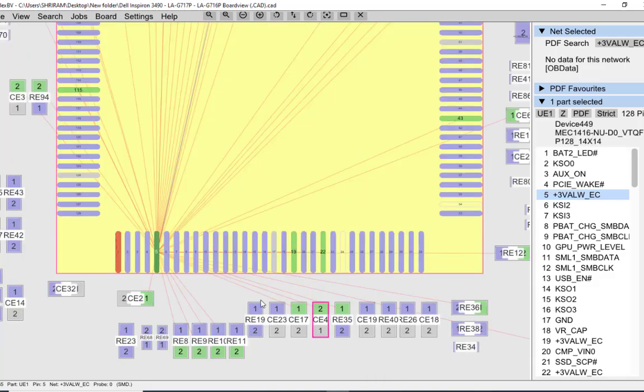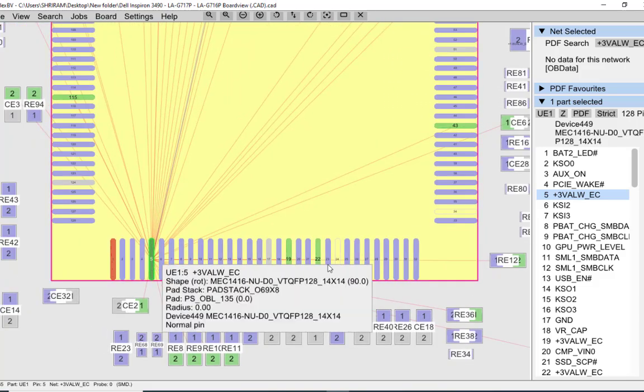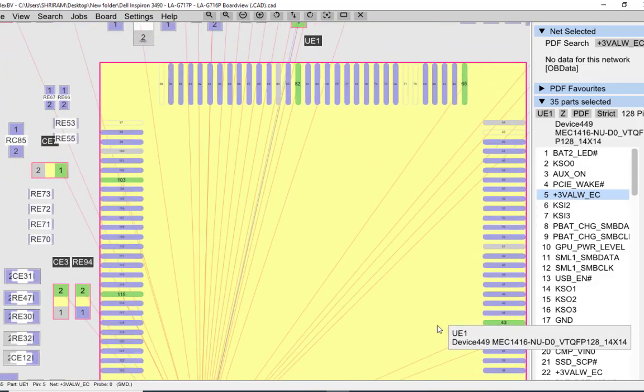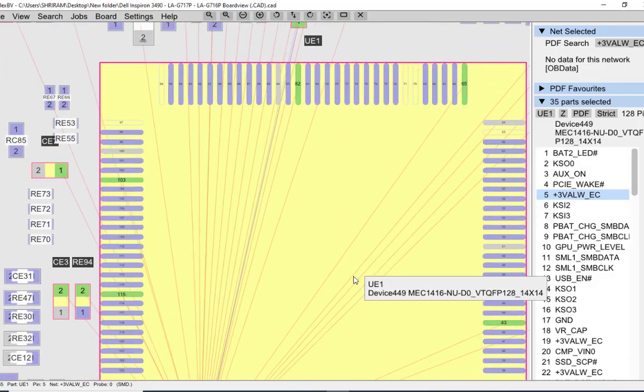So we can check this 3 volt here. Any of these pins you can check. You can check here, you can check here, you can check these resistor arrays here. You can check anywhere. Here 3 volt is supposed to come, so you can check 3 volt here. Okay, and if this 3 volt is not coming, then your laptop is not going to turn on. So you go back to the 3 volt section and check why 3 volt is not coming. First, the SIO needs the power. The SIO should get this 3 volt. So you have to check any of these pins. After that, once you get the power, the next things are the EC reset, the AC in signal, and the lid switch.